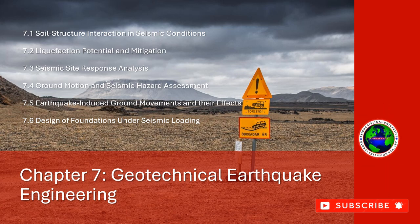Soil compaction. Compaction of loose soils can increase their strength and reduce settlement during seismic shaking. Grouting and stabilization. Techniques such as cement grouting or chemical stabilization can improve the strength and stability of soils, particularly in areas with weak or liquefiable soils.